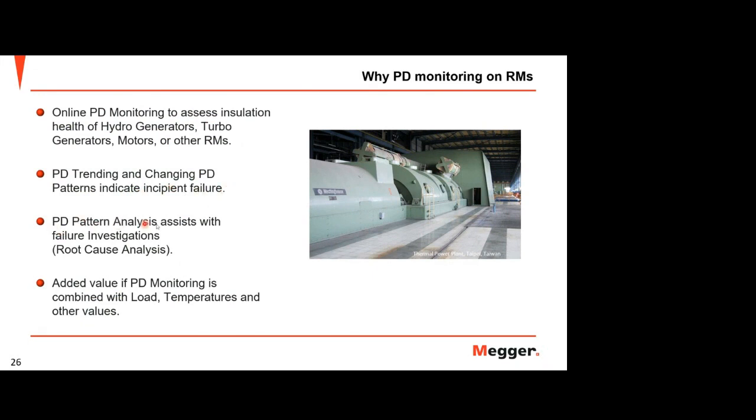PD pattern analysis assists with the failure investigation. You can do root cause analysis, and it is better if PD monitoring is combined with the load, temperature, and other information, because all this information affects the PD behavior.